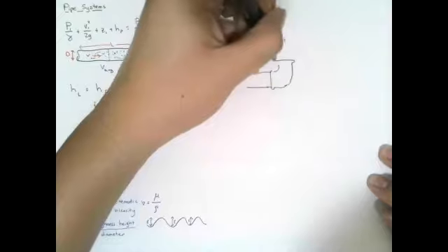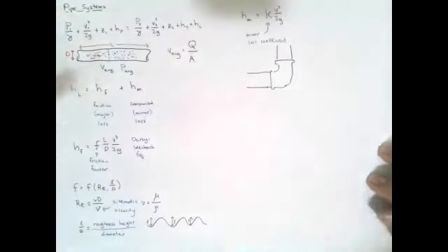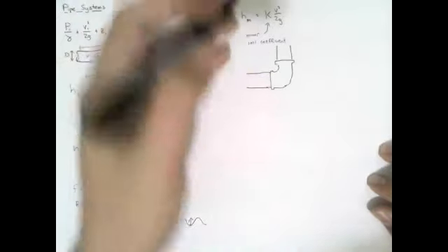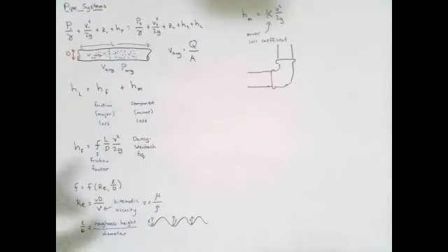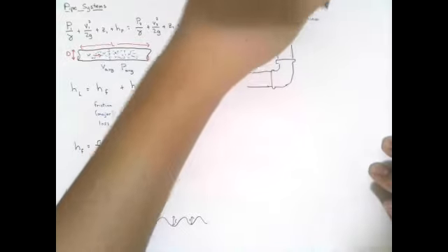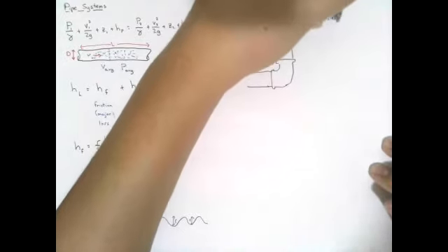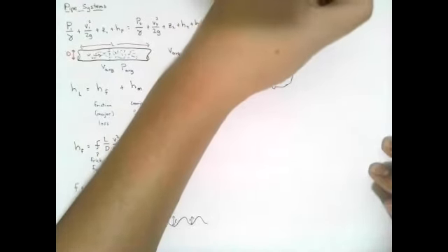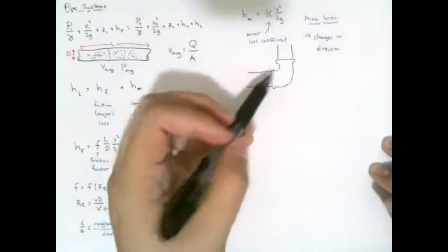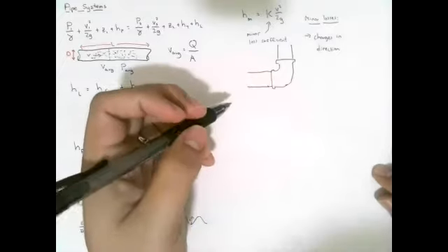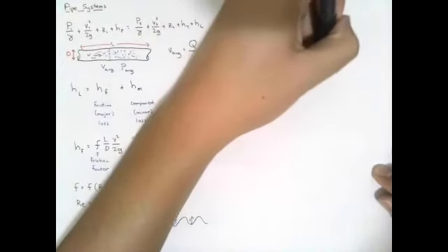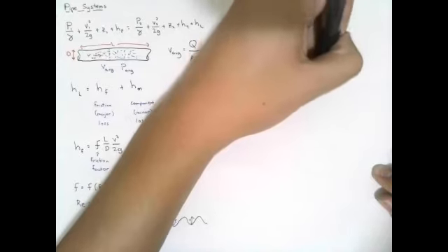And it's kind of hard to come up with a definition for things that the minor loss coefficient covers because it essentially covers everything except friction. But I think we can say that minor losses should cover, among other things, any changes in direction, such as this fitting that changes the direction by 90 degrees. But then they should also cover any changes in geometry.